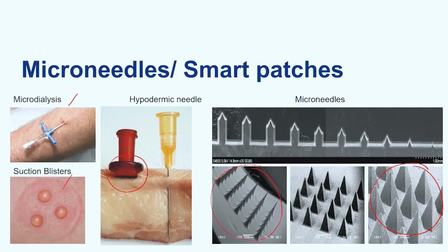Be able to scale it and to have uniformity, to have consistent structures, because when we talk about electrochemical sensors, the signal that you get from your electrochemical sensors is directly proportional to the surface area. So if you have different microneedle arrays of different dimensions, you will be getting different signal values, and you wouldn't be able to make sense of those unless you did a back calculation. So it's very important that you have uniform structures, uniform geometry, uniform surface areas. And some of these studies will be about how we were able to achieve those.